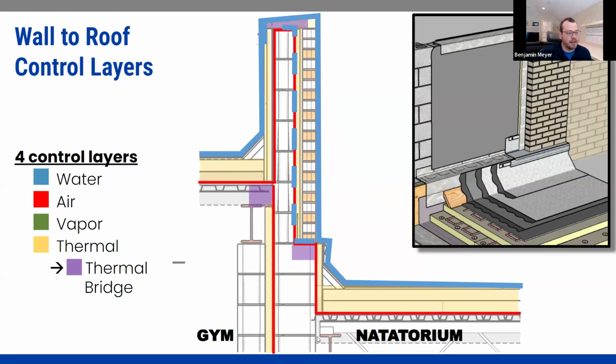So this may be a reason to have your air barrier here on the inside and also a vapor retarder to prevent condensation from getting up into this system and showing up potentially as a leak on your gym side if it hits here. If you haven't separated those two, you have the ability for warm, moist air to get into this space and create staining and condensation, and it's hectic for your roofer who's trying to fix a leak that may not exist.